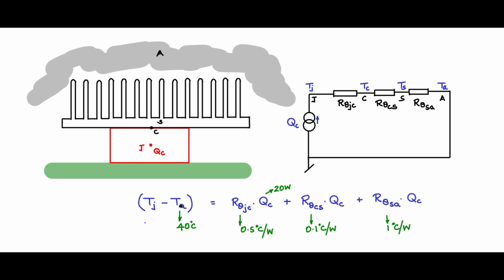Of course this can also vary from place to place. For that particular place you should take the ambient, and if it is within an enclosure, you should take the ambient within the enclosure. Normally if a component is within the enclosure, the worst case ambient within the enclosure is taken as 50 degrees. So now you can compute Tj.